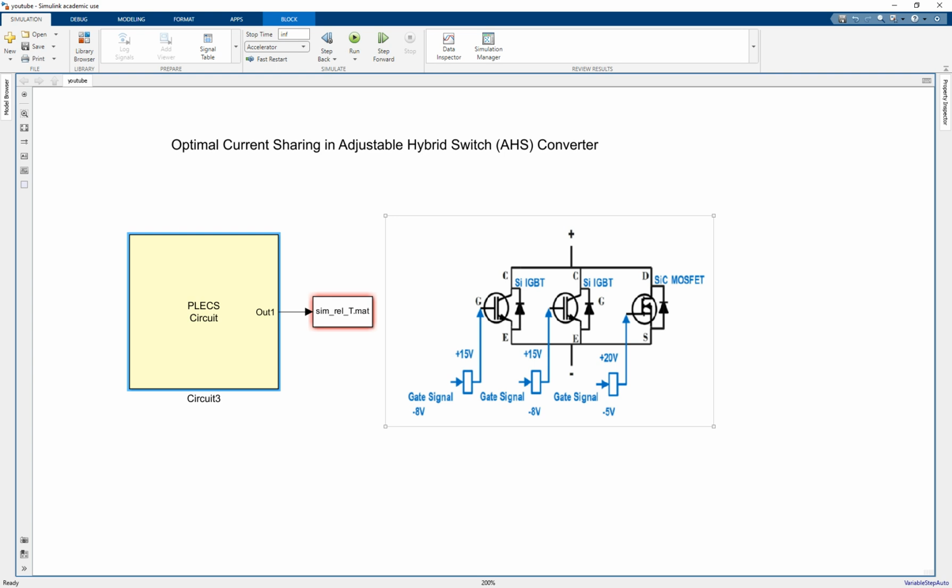But then from power loss to the temperature, I did it manually. I had to do it manually. I'm going to come to this later on. But the reason is simply I wanted to know the temperature because for my simulation temperature was a state variable, and I needed to have access to the temperature every time continuously. So I only used Plecs to calculate the power losses.